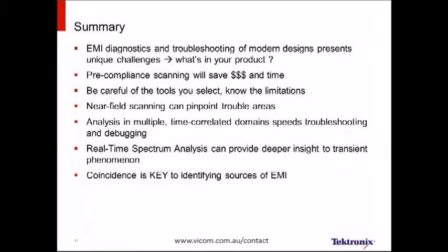EMI diagnostics affect us all. Pre-compliance scanning will not only save us time, but a lot of resources as well. But we have to pay attention to the tools that we select and recognize their limitations. When we start looking at EMI diagnostics specifically, near-field scanning will help us pinpoint trouble spots.